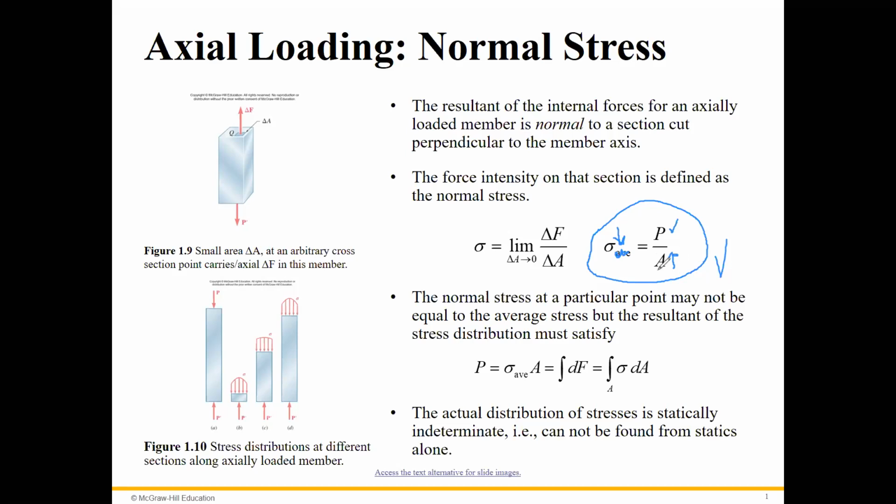But if you pick the weak cross section, then it's not good, right? Yes. So when the stress is greater than P over A, that means it's unsafe, so we have to raise the area. I just want to clarify that. If sigma is greater than sigma allowable, then this condition is not good, and we need to increase this, right?